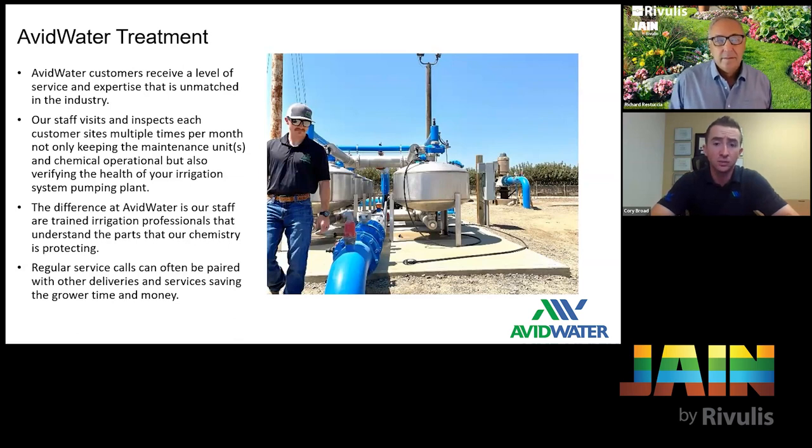And I would say that when you look at the pressure of the system, and if every time you go out there it's 38 PSI and it's this flow rate, and things have not changed, you feel comfortable as a service provider and hopefully as a grower. If I notice something on a service report where I go, Richard, the pressure's up a little bit and your flow's down by 50 gallons a minute, maybe you haven't seen it yet in the field, or the guys just haven't found where it's happening, but we need to look at something that may hopefully set into motion a flushing protocol, right?